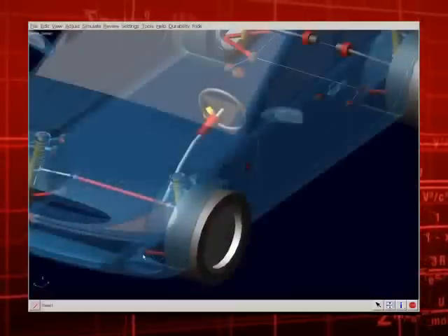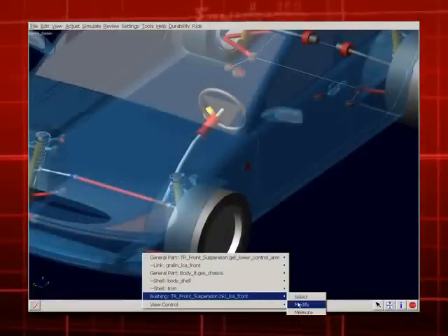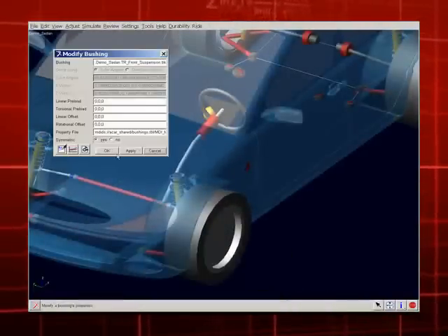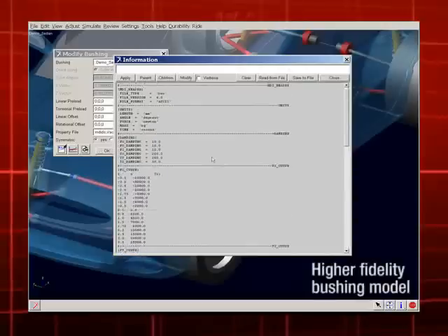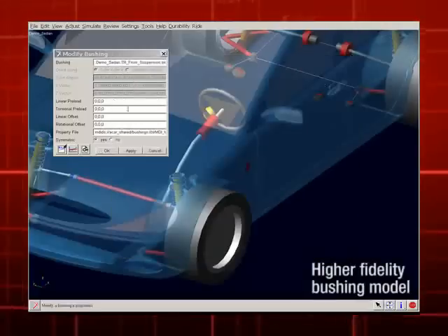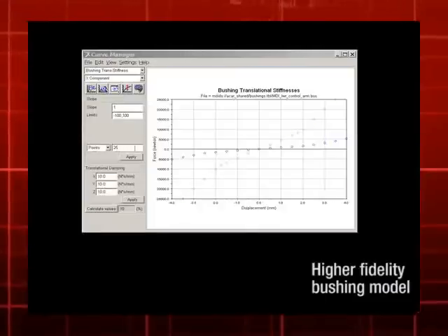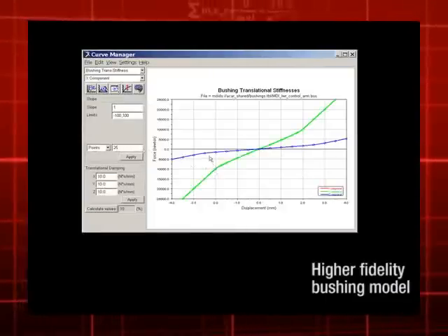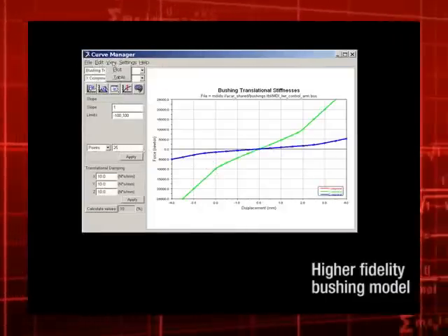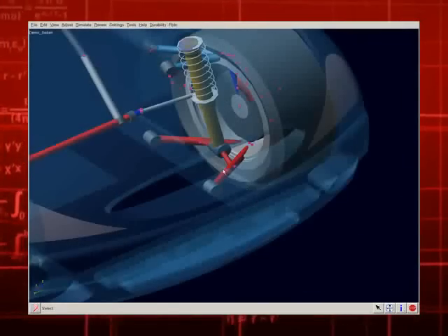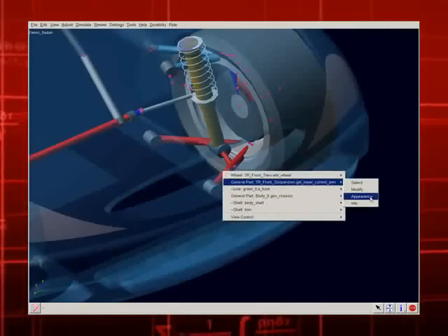The engineer in the ride group next uses the handling model as a starting point and changes to higher fidelity components to see how they affect the simulation results. Adams car provides detailed bushing and damper models for such ride analyses. At this point, the model would consist of rigid parts.